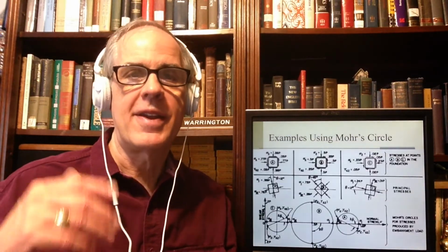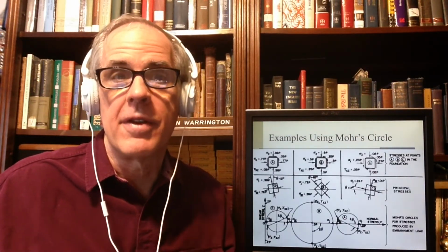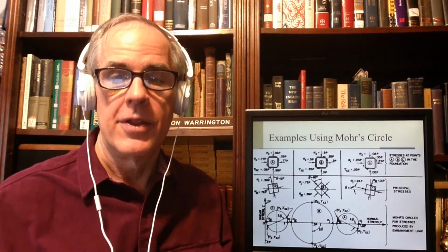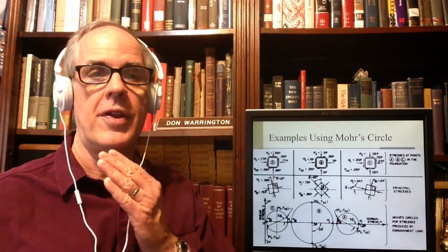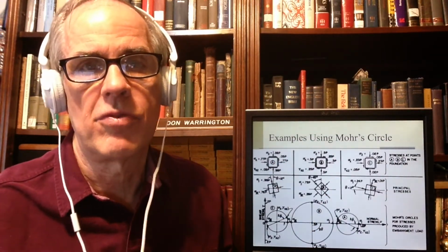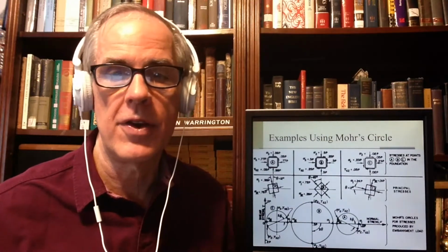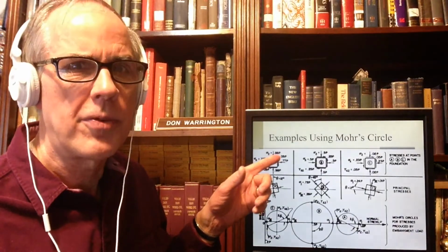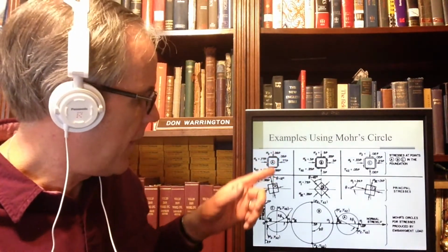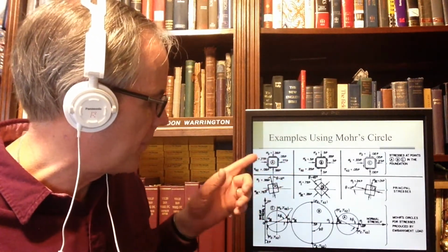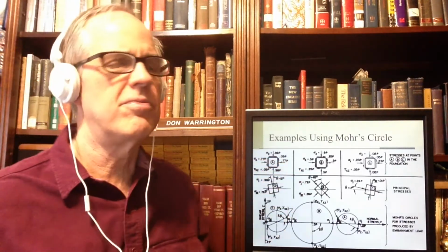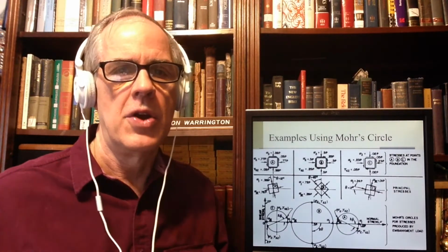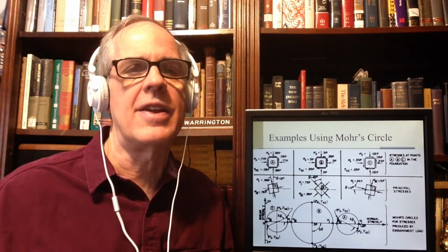Even though, because it's not infinite or semi-infinite or whatever, that doesn't apply. But the first one over on the left side is really very heavily loaded. You can see that. The sigma Z is 0.9 P. That means it's almost a uniform surcharge this way. And then we have 0.77 P this way, and that's mostly due to lateral loading and Poisson's ratio loading. We're going to leave that. It just is. It's something you understand.